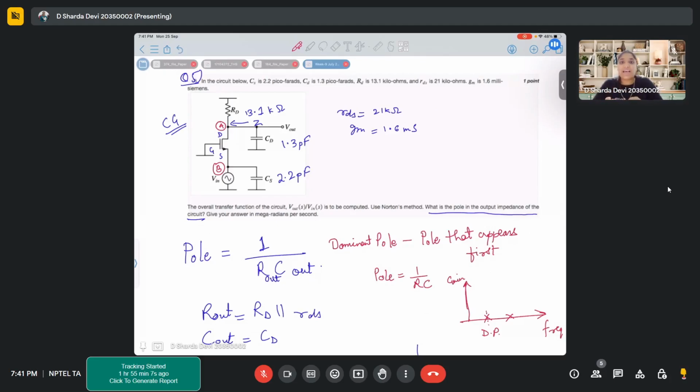Junction capacitance is formed where you see a junction forming, which is a junction between, let's say, PN or any type of junction, like N plus N, P plus P. These types of junctions are also junctions, right? In those places, the capacitance coming into the picture, we call a junction capacitor.